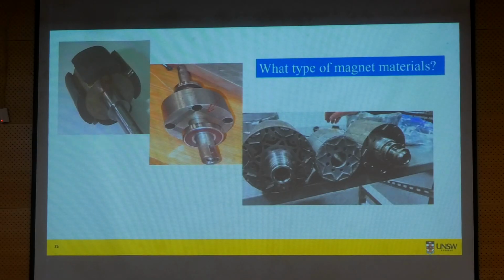In this design, they're trying to improve the reluctance component so that they can use smaller magnets. You can see they are using quite thin or small magnets, so magnet torque will be less. If magnet torque is less, how do you still get the same total torque? You want to increase the reluctance torque. That's why I believe they are doing all these things.